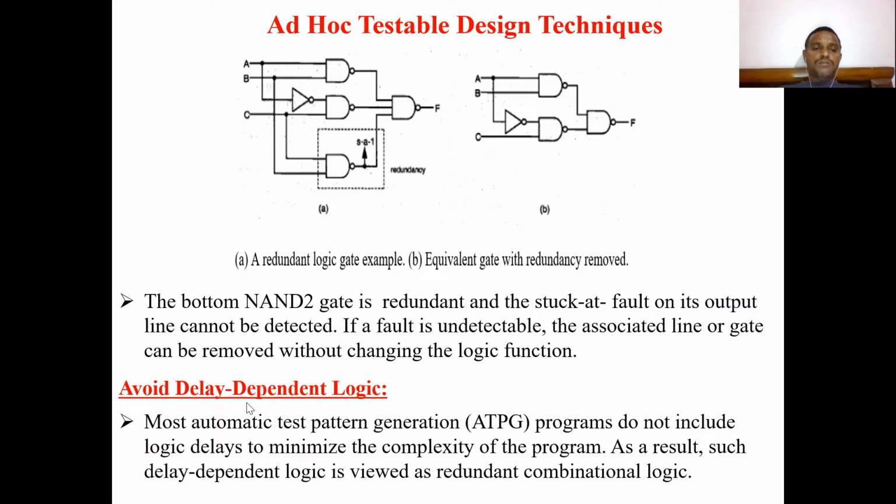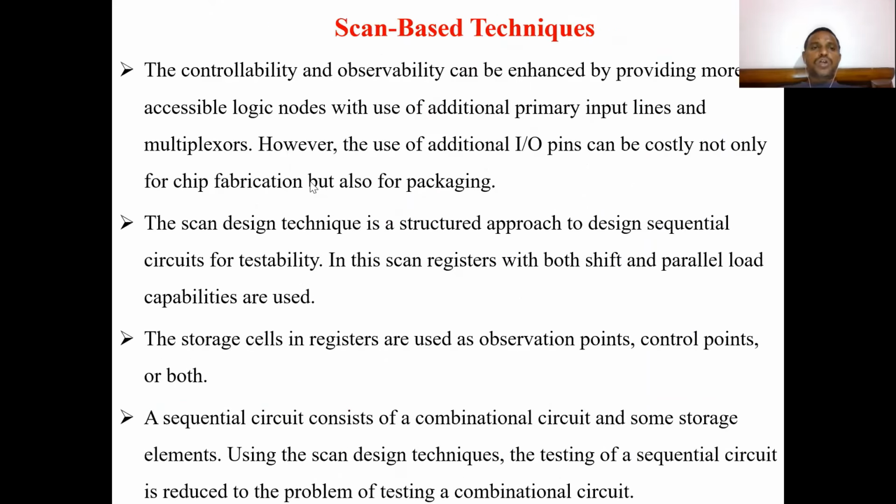Next one is avoid delay dependent logic. If any delay dependent logic is there, we have to avoid that. Most automatic test pattern generation (ATPG) programs do not include logic delays. Generally, these test pattern generators do not include logic delays, to minimize the complexity of the program. As a result, such delay dependent logic is viewed as redundant combinational logic.